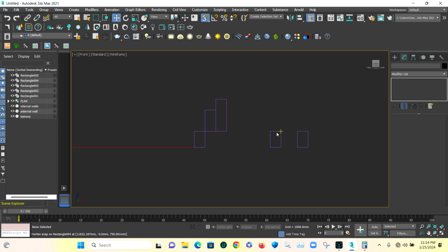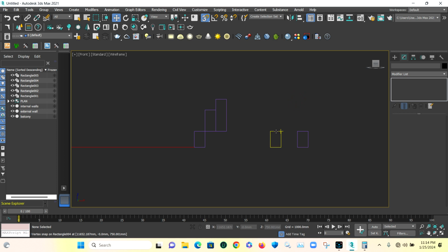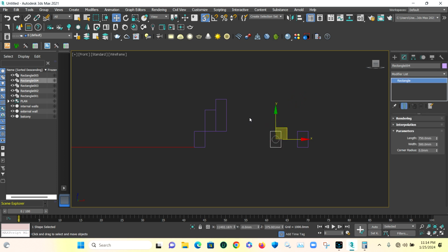Now next I want is my lintel level, because after my toilet window and this window, next thing is lintel level, except you have any other level you want to acknowledge. Maybe you have some type of windows that start from somewhere, whatever, you represent them here. Now I select this other one. I want this to be my lintel level, and I want my lintel to be at 10 courses. It can be at 9 courses. You are the architect or the engineer, so you make your choices, anything you want.